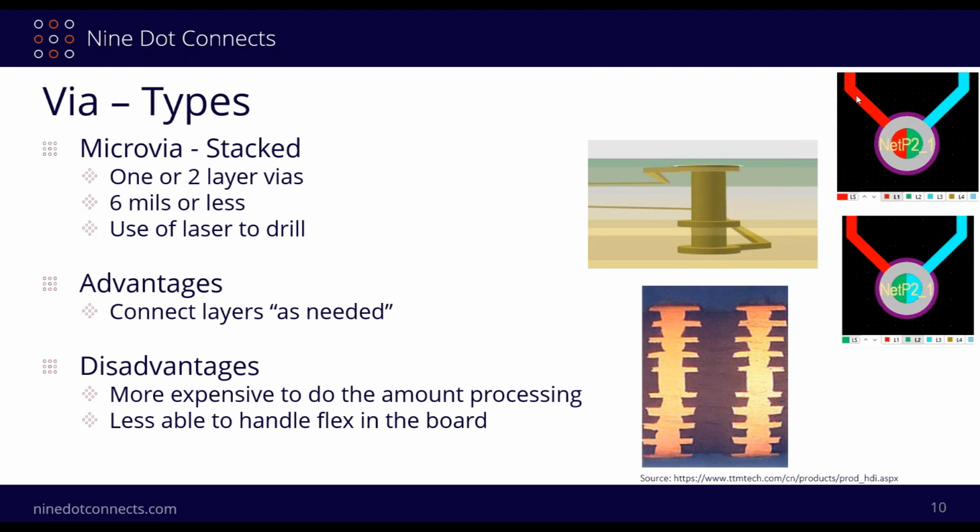So what I did here was basically I routed this out. This was a one layer, so I set this up in the drill pairs here, and then I just stopped. And then at that point, I continued. I put down another one of these vias here, and then I continued along. So that's why you see what I'll call the poker chip here.